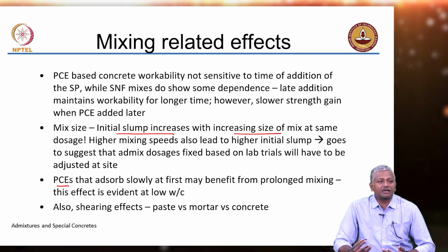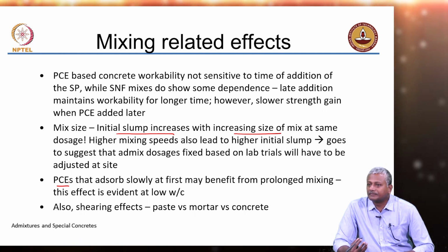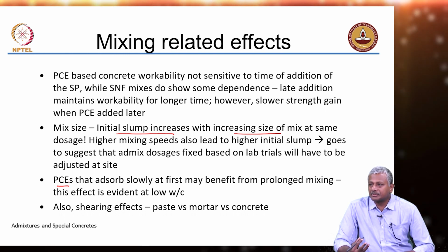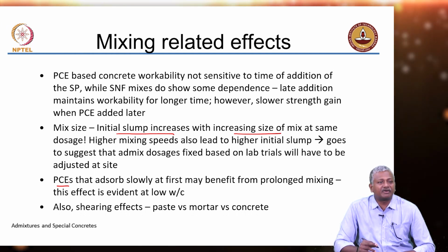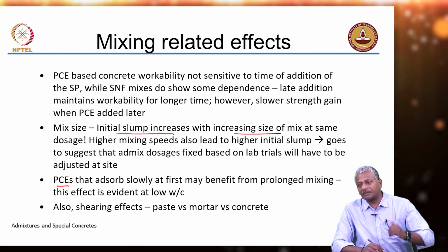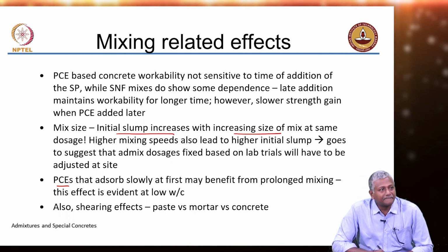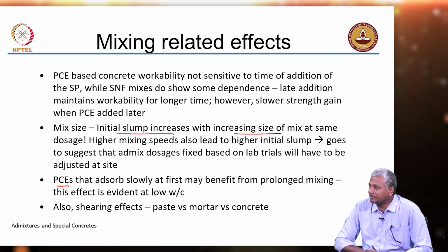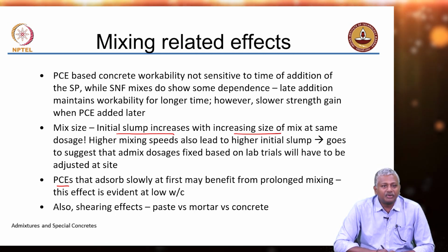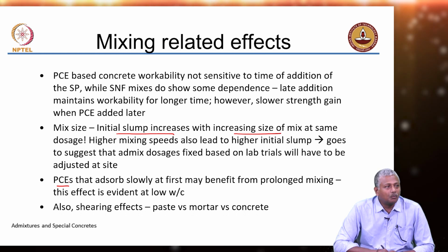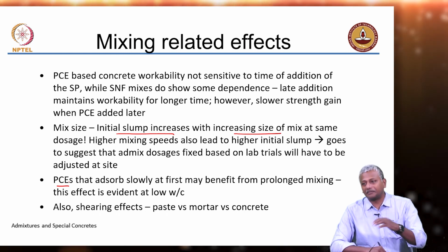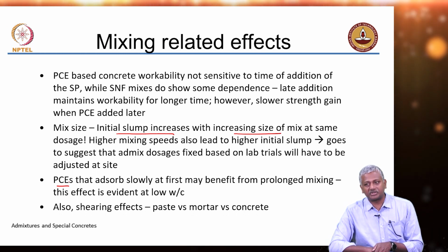You need to fill up a truck which is of how much volume? About 6 cubic meters, yeah? 6 cubic meters on an average, and your mixer is 0.5 cubic meter. So, that means you need 12 times mixing to happen to fill up one truck, right? 12 times concrete has to be mixed to fill up one truck. Now, if you take 2 minutes instead of 1 minute, you are doubling the time that your entire operation lasts.